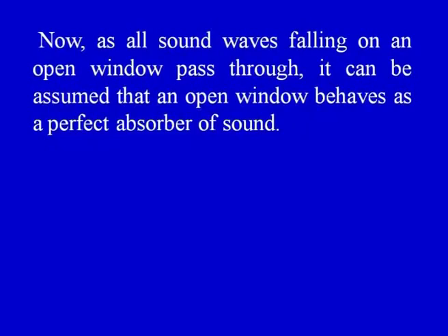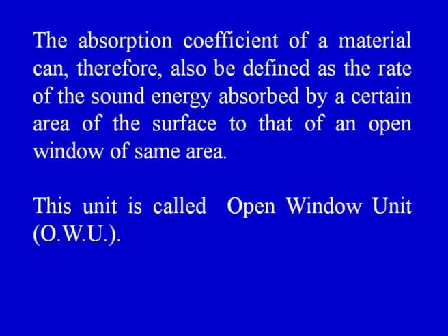This is the standard definition of any absorption coefficient. Now, as all sound waves falling on an open window pass through it, it can be assumed that an open window behaves like a perfect absorber of sound. The absorption coefficient of a material can therefore also be defined as the rate of sound energy absorbed by a certain area of the surface to that of an open window of the same area. This unit is called open window unit, OWU.